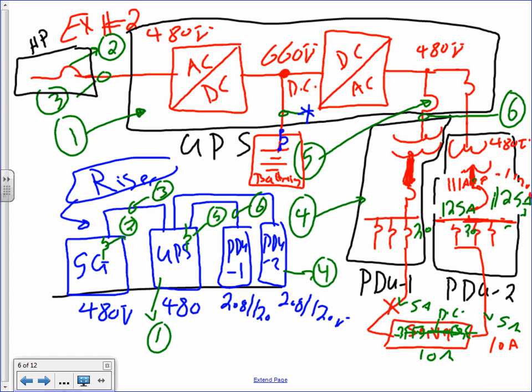The battery system is your backup, typically 15 to 20 minutes, no more than that. Then they invert it back into AC and transfer it into two panels. Each one of them typically has a transformer inside it. And from these two panels, they feed my server.